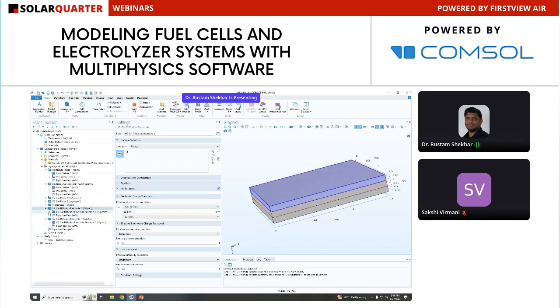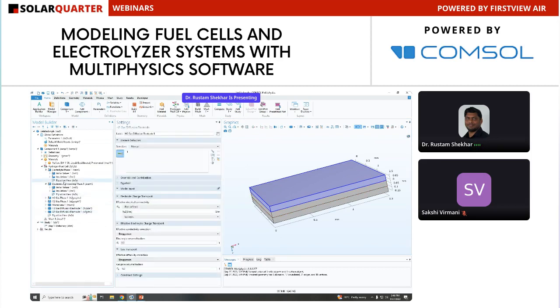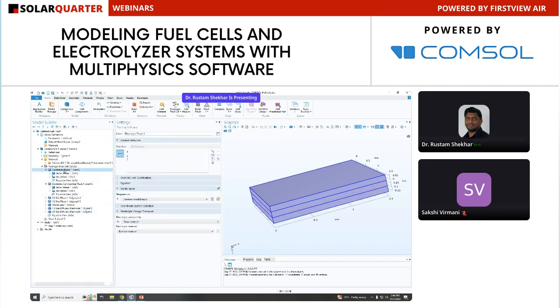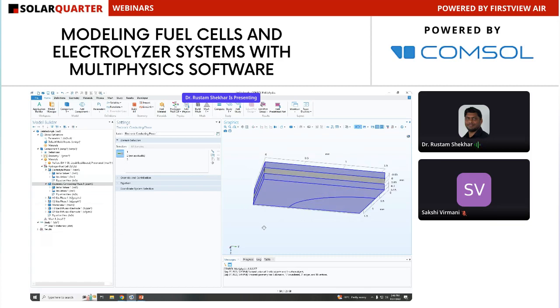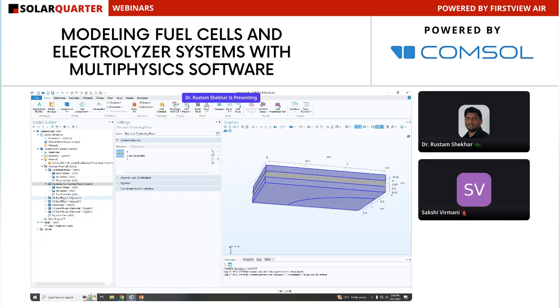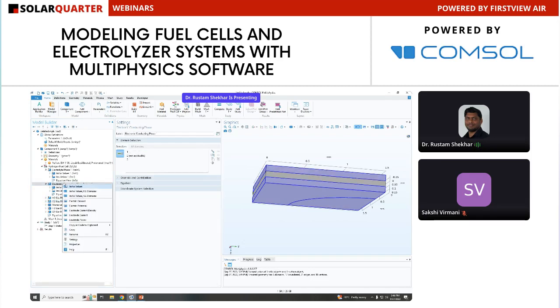Now I have assigned the membrane, H2 electrode and O2 electrode, and the software will automatically detect that the electrolyte is available in all three phases, the electronic phase is being solved only in the top and bottom layers, and then you have the H2 gas phase and the O2 gas phase. With this, you can just specify at what mode you want to operate.